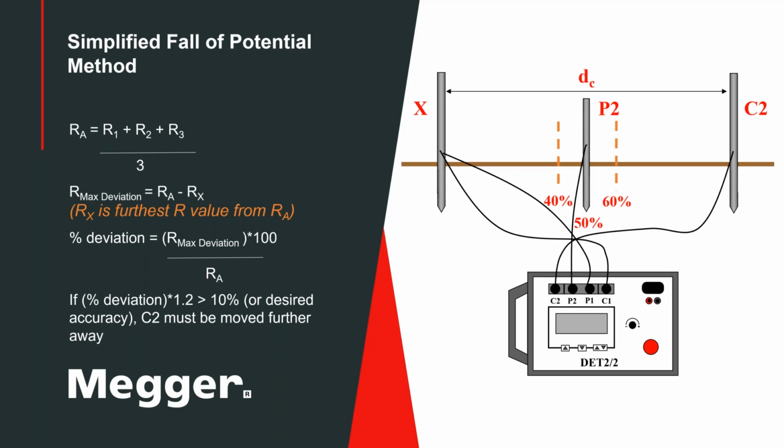You're going to take a measurement halfway the distance to your current probe, and then one 10% in and 10% out. And then you'll see on the left there a mathematical crunch. So those 3 measurements are R1, R2, and R3. And you're going to plug them into that little mathematical crunch. And what that does is calculates out the percentage error for the average of the 3 measurements.